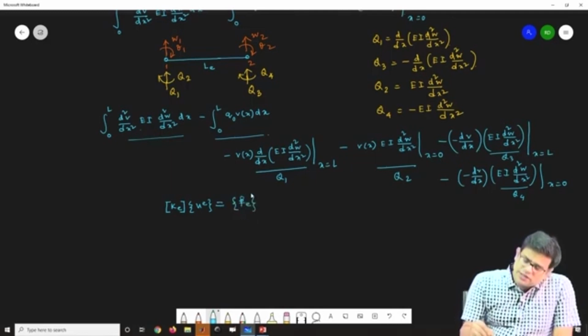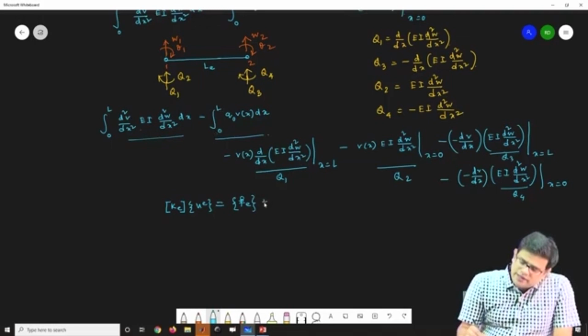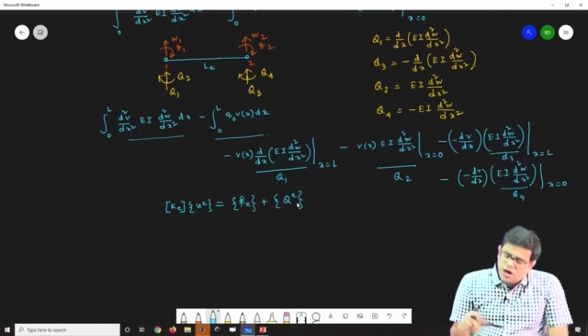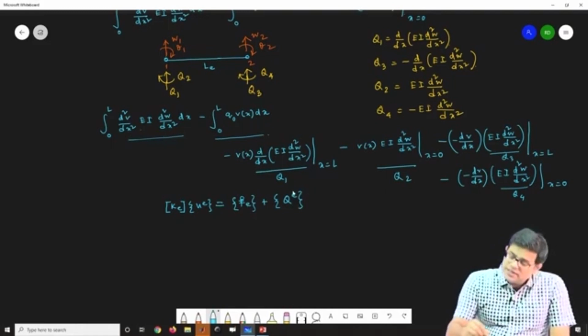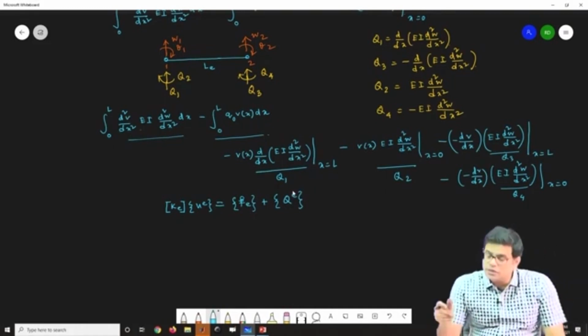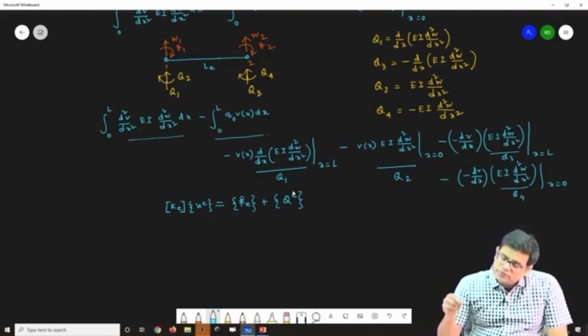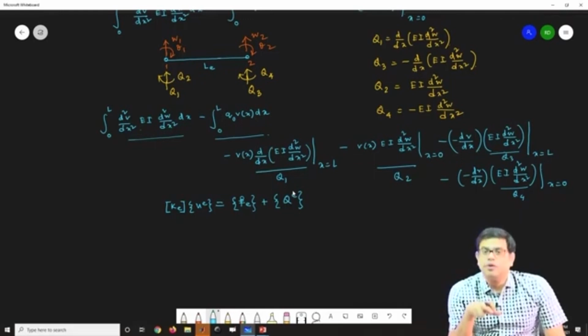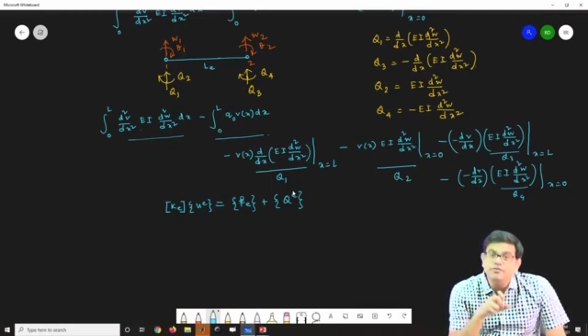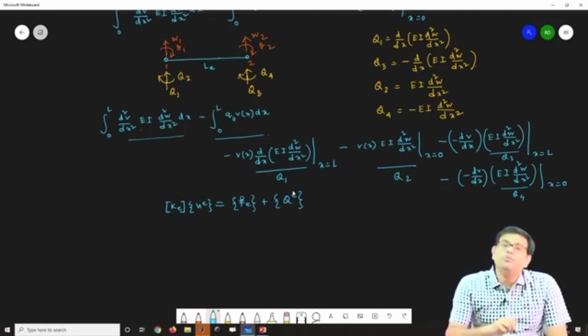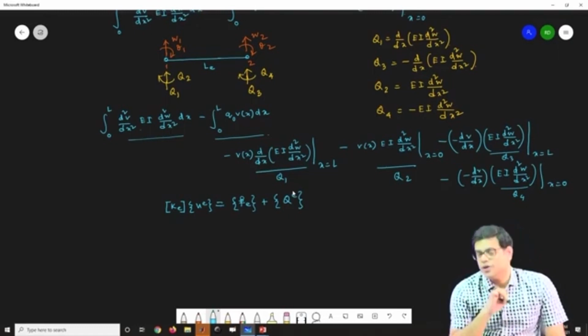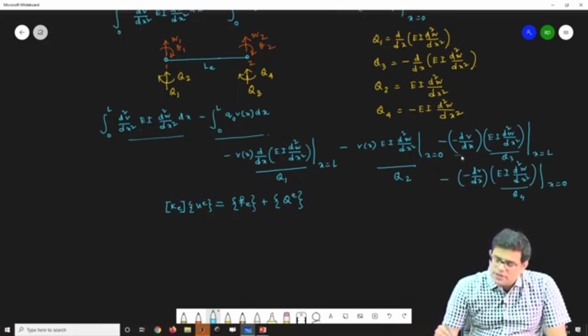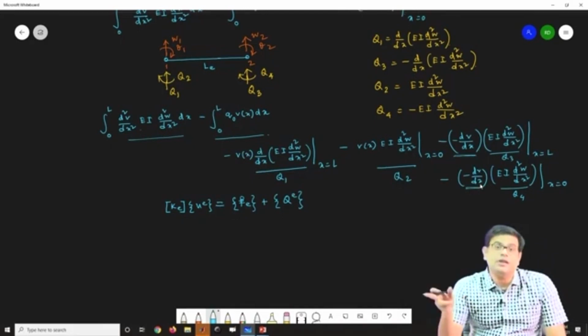Fe will come from the body force, and QE will be the boundary reaction terms. If you remember the bar problem which we discussed in the previous lecture, the interpolating nature of the slope is very important here, because this quantity has to vanish at the other nodes.